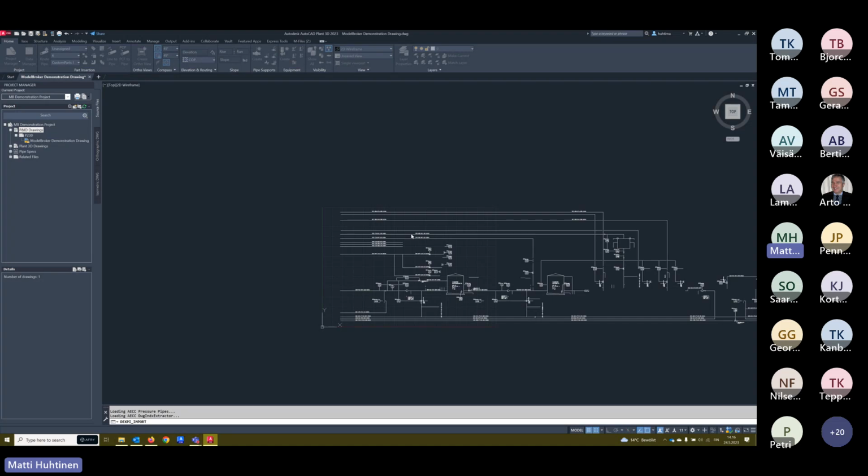And of course, when we use this model broker, we still need to understand how Plant 3D works. So we need to map all symbols with this mapping XML. We map all symbols to the correct Plant 3D class. In the THTH standard, A2101 is for the general valve symbol, and 0101 is for a tank, etc. So with this model broker, we map all components to the correct Plant 3D class.